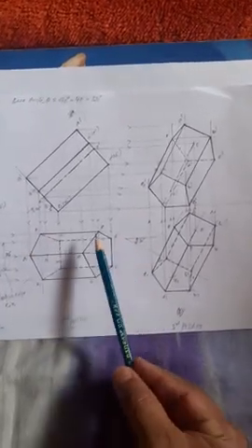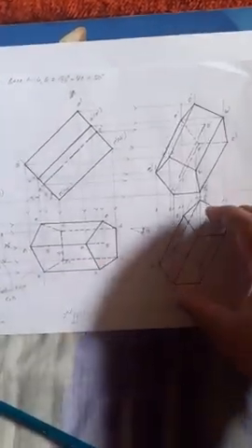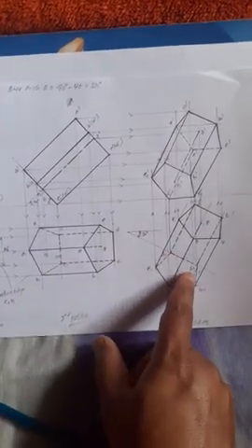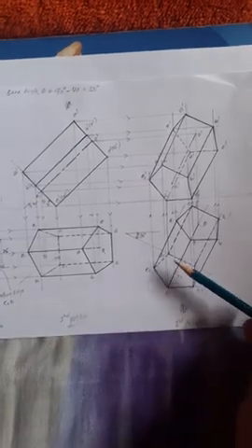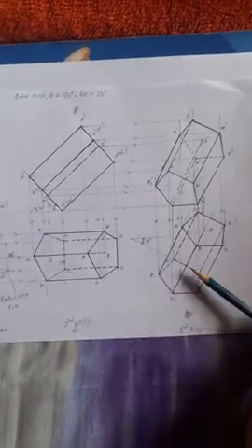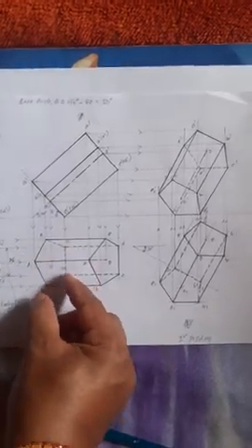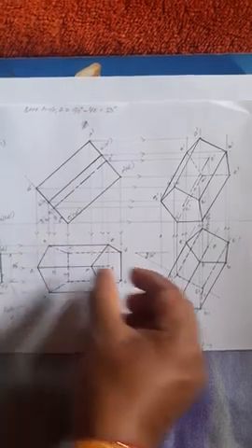That's very important. Now when you rotate this solid kept on the 30-degree line, once you place D1 C1, what about E1, A1, B1? Those will come below the 30-degree line, right? Then how do you place these corners? Take C1 B1 as a radius, that is equal to D1 E1.